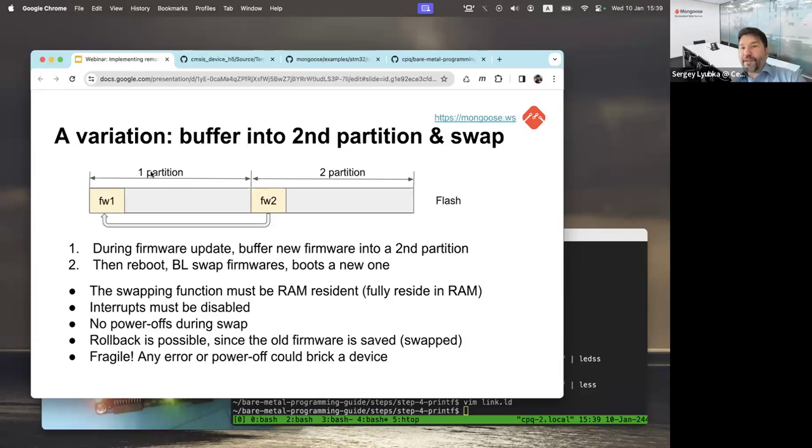Usually the rollback mechanism is implemented like this. When a new firmware starts, the bootloader starts a hardware timer for a certain period of time, for example, 2 minutes. It writes a flag somewhere, it might not be in the flash, could be anywhere, that this firmware is still testing. It's not verified firmware.